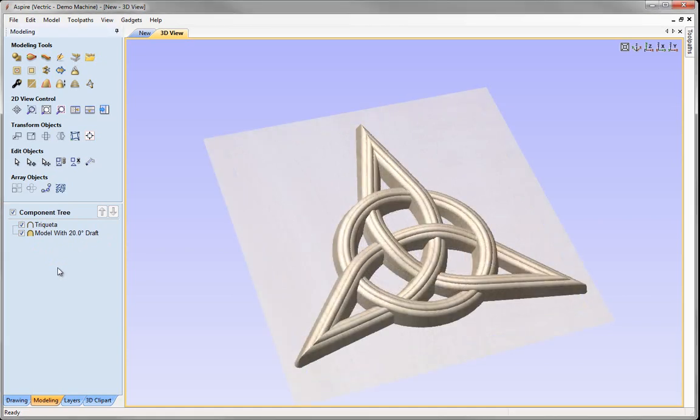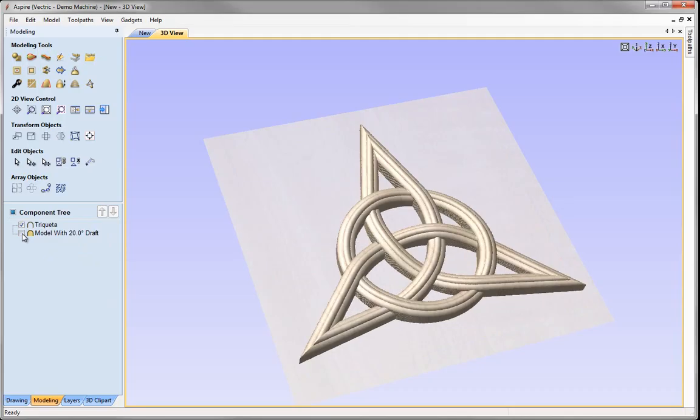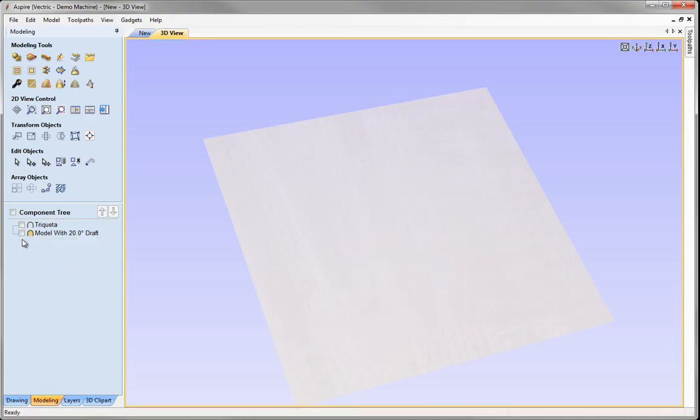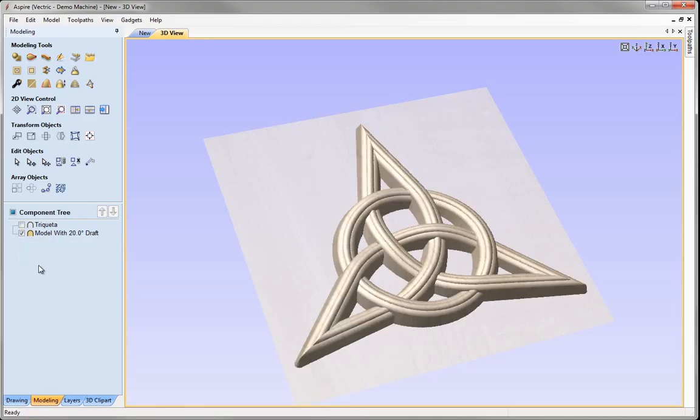As this shape is set to merge, it just obscures our original shapes underneath it. If we undraw it, you can see our original there. In this case I'm just going to undraw the original, switch on our new one. You'll notice there something that was popping up, which is another new feature. If I hover over a component, then I get a tooltip that tells me its combine mode, whether there's any base height, and its total height. This is very useful to just hover over and see the information about the different shapes in my part.